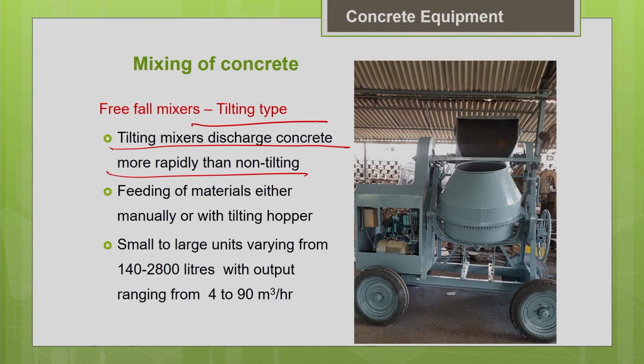That is why we should not waste time. Once the concrete is made, we should immediately discharge it and carry it to the desired place. We should never waste time in the preparation of the concrete. That is why tilting mixers are very helpful, because their discharge rate is much faster when compared to the non-tilting mixer. So the chances for segregation are less when you go for tilting mixers.